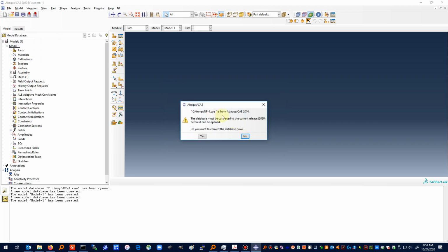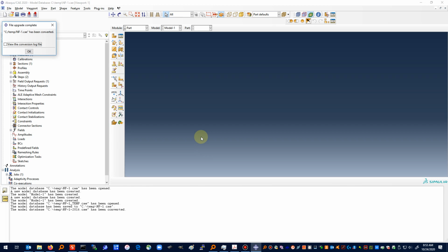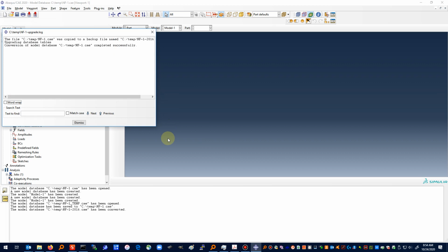Okay, so it's from ABAQUS CAE 2016. The database must be converted to the current release, which in this video is 2020, before it can be opened. Do you want to convert the database now? And so I'm just going to select yes. So every version of ABAQUS, we can look at the conversion log, is slightly different in the format of the file. It can recognize what version of file it is and automatically convert that to the upgraded CAE database.